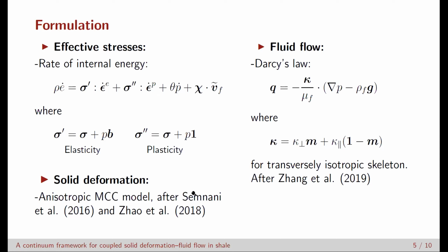As for the constitutive modeling for solid deformation, we use the anisotropic modified Cam-Clay model after Semnani et al. and Zhao et al. Finally, for fluid flow through porous space, we use Darcy's law, and we use this anisotropic permeability tensor, which is also characterized with the two components along the bed normal and bed parallel direction, together with the microstructure tensor to capture the anisotropic behavior.